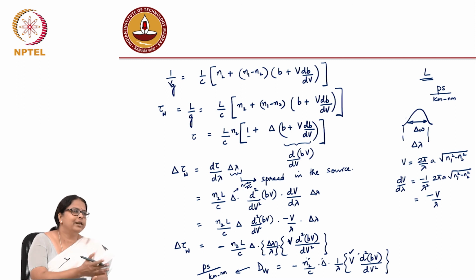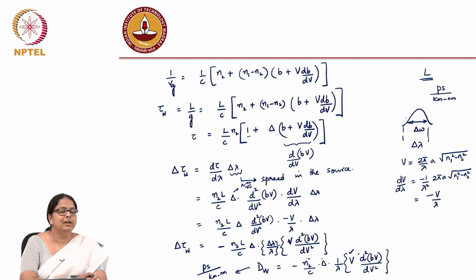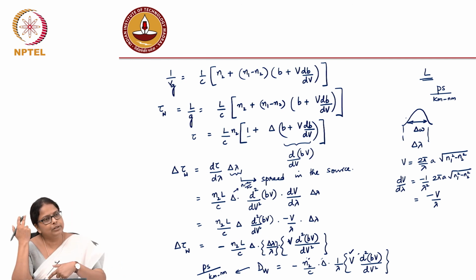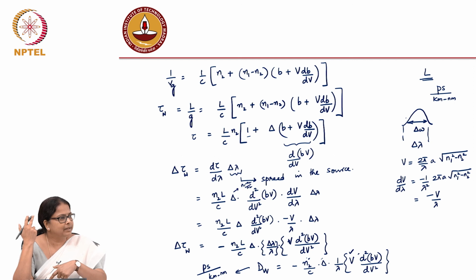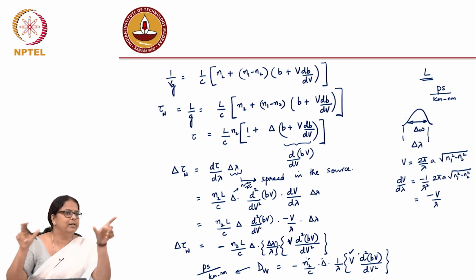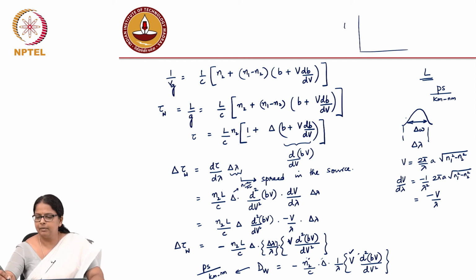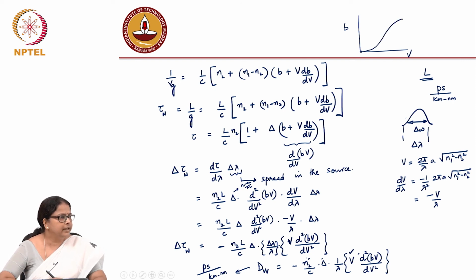How do I get that product bV at that particular wavelength? So, how do I first do the second derivative? How do I get to that point? So, you have to go back to the universal bV curve. Remember, we had plotted for the fundamental mode b versus V is universal. We had some curve like this. Fundamental mode did not have a cutoff, it was something like this. And the first cutoff for the first higher mode was what? 2.4, right?